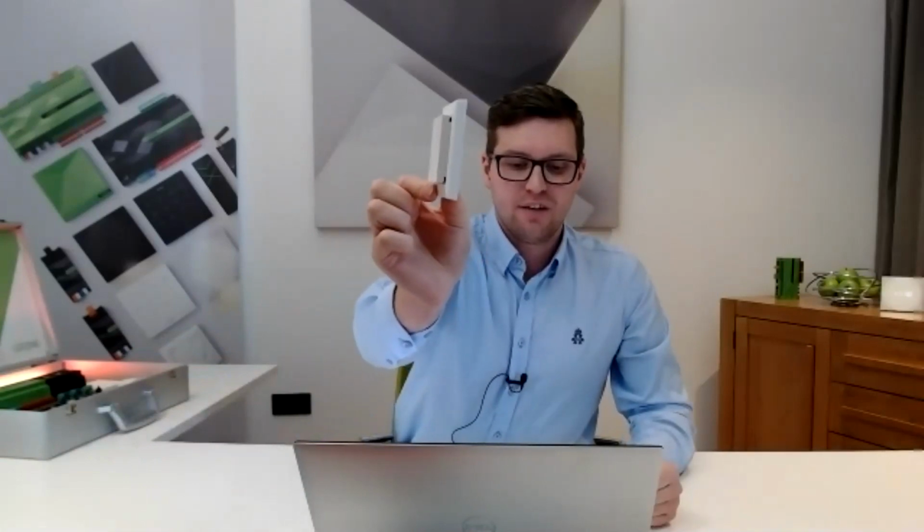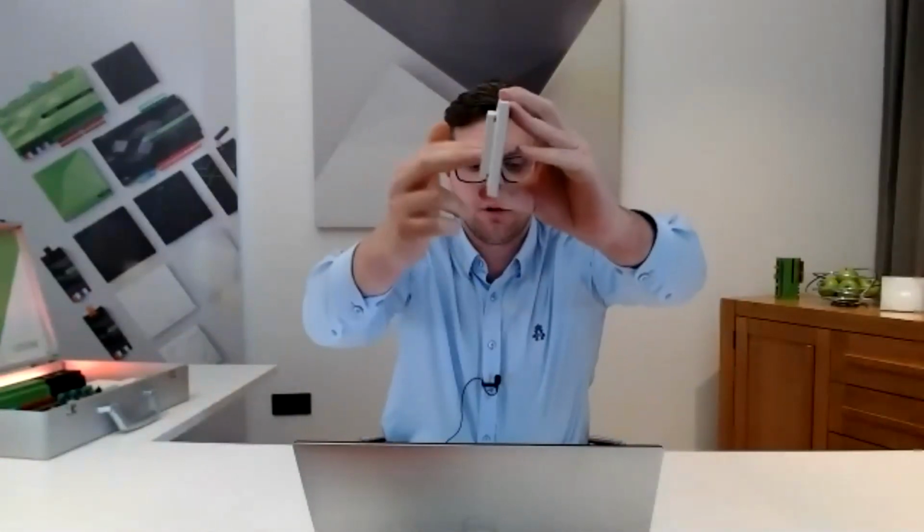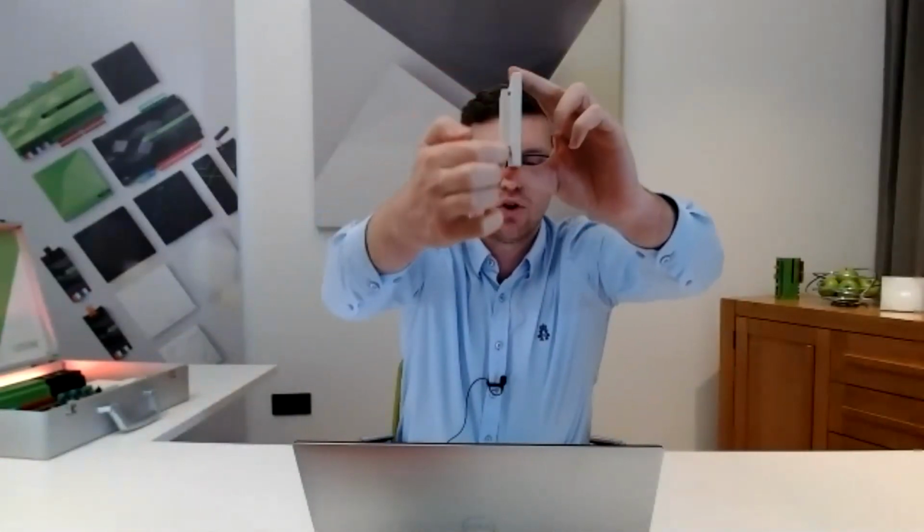In addition to the touch switches for temperature sensing, you also have the option of a room comfort sensor. So a room comfort sensor, as you can see, physically quite similar to a touch switch, except the front of it is raised. And that's again to allow good airflow around the side. Room comfort sensor, again, tree or air. Really importantly, the air version of the room comfort sensor is temperature and humidity only. The tree version, which is this version here, is temperature, humidity, and CO2. The reason for CO2 in the tree version is for ventilation control in addition to room climate control.